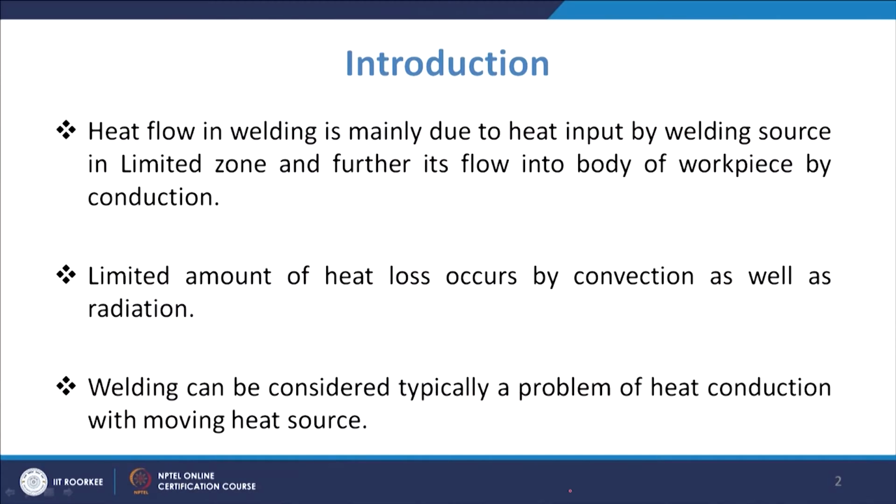We will try to understand the fundamentals of the heat flow equations, and in our coming lectures we will try to understand the temperature distribution in welding. In this lecture we will look at the basic equations which govern heat flow in welding. Heat flow in welding is basically due to the heat input by the welding source in a limited zone, and it further flows into the body of the workpiece by conduction.